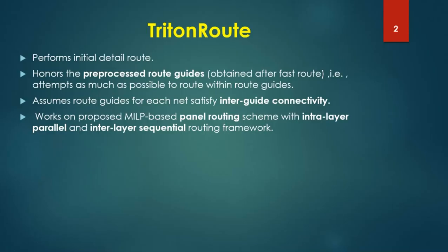And it's actually based on MILP parallel routing scheme with intra-layer parallel, inter-layer sequential routing frame. In this statement, I just want you to focus on the intra-layer. Intra-layer means within a layer. So say for example, you are doing routing within say metal 1 layer. So in this Triton route, using this MILP based panel routing scheme, in M1 the routing happens in parallel.